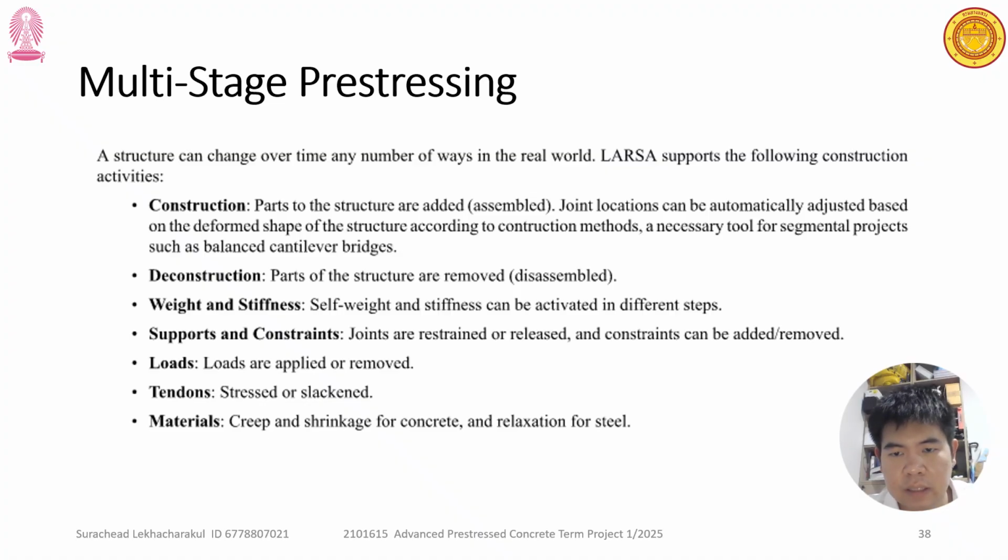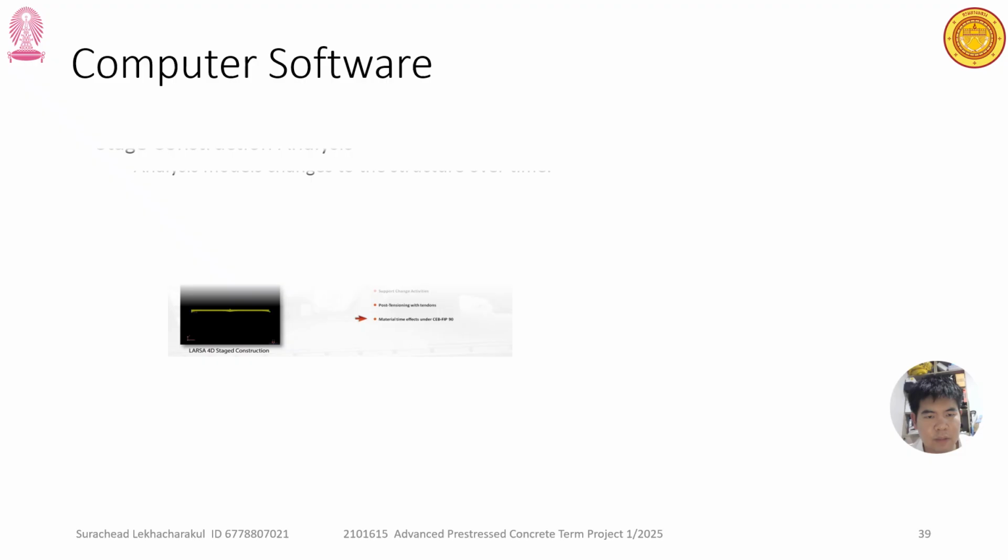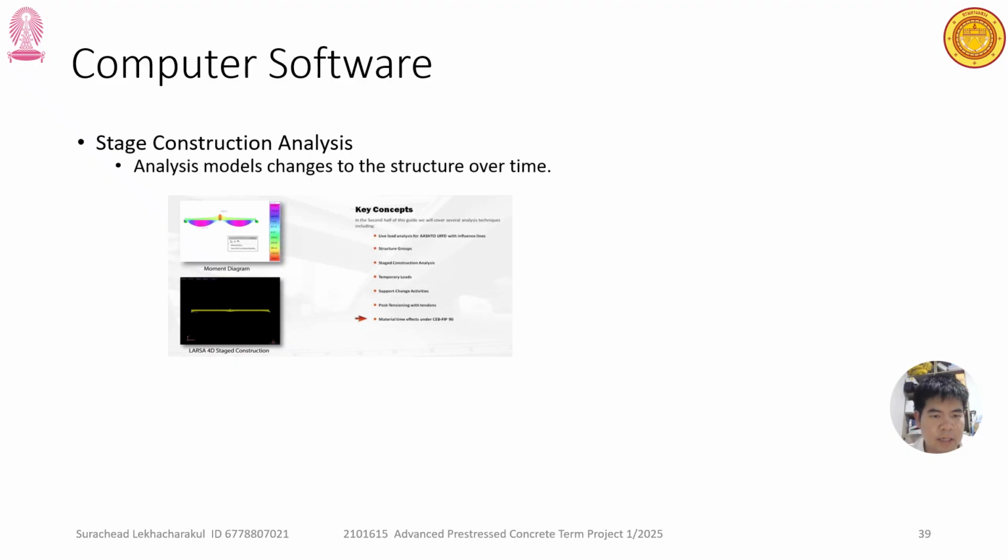LARSA supports the following construction activities: construction, deconstruction, because some parts have to be removed like temporary structures, so weight and stiffness will change; supports and constraints added or removed; loads applied or removed; and tendons and materials depending on time, creep and shrinkage for concrete and relaxation for steel.